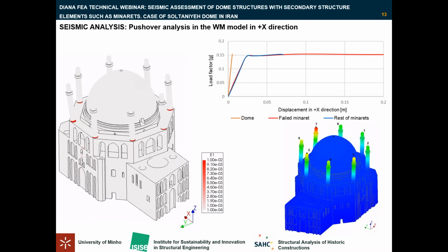This analysis accounts for the nonlinear behavior of materials, and the seismic action is simulated through horizontal forces. Pushover analysis allows to determine the capacity of the structure to withstand horizontal loads and is considered a powerful tool for assessing complex unreinforced masonry structures.